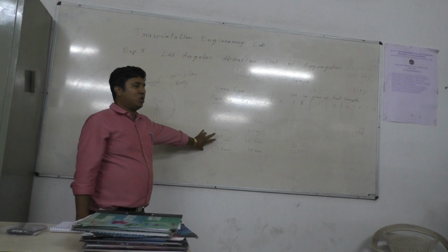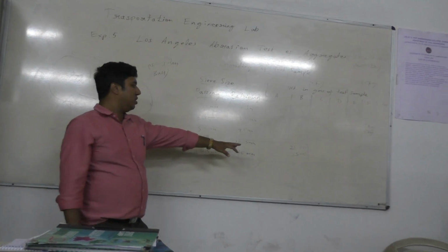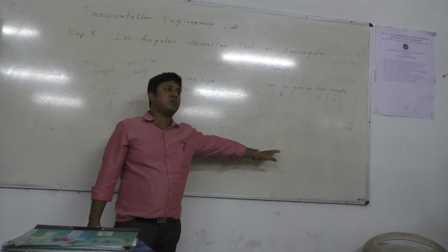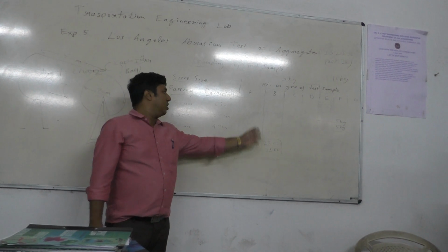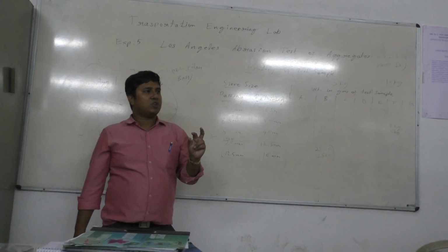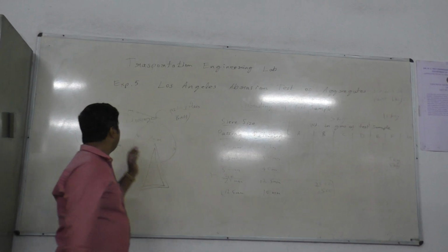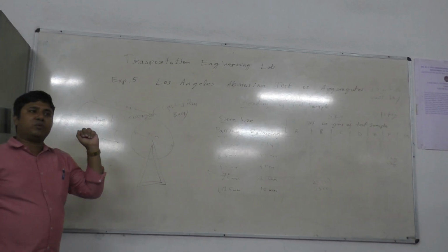Once we take this sample for our grade B, we have to take 2.5 and 2.5 kg of weight of the aggregate from the chart, and we will choose the abrasive balls. The number of balls, as I told you, is 11. So we will take 11 balls.